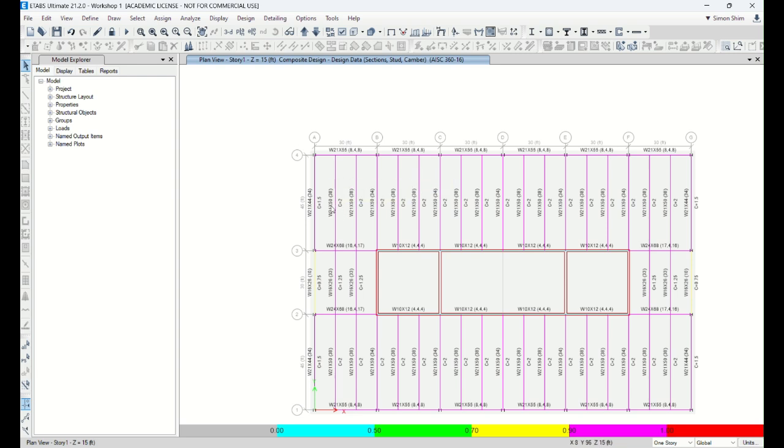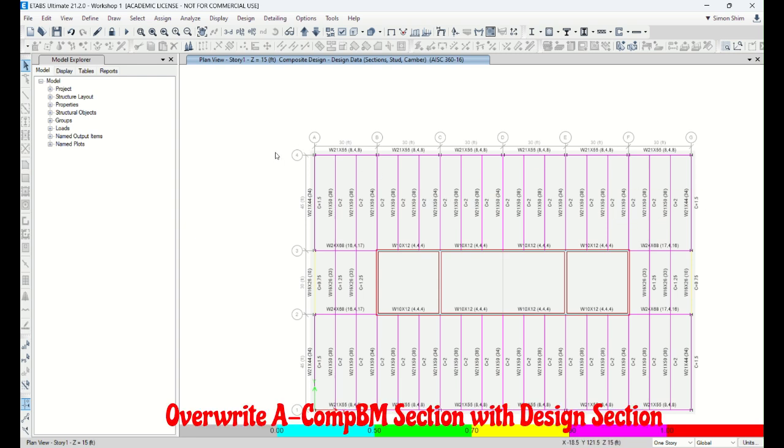One thing you need to be aware of is typically the beam and girder sizes. Usually we choose the girder a little bit deeper than the beam, so that we don't need to cope the girder or the beams on the top side. If a W21 is framing into a W21, you need to cope top and bottom, which may add some fabrication cost. So typically a girder deeper than the beam is more competitive, with cost savings.